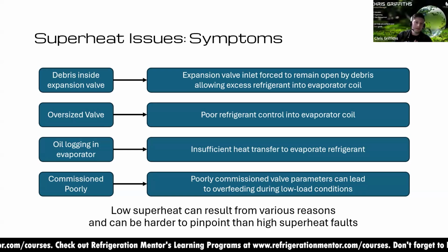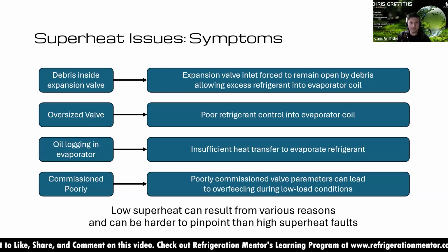So honestly, having that visibility over a prolonged period of time is invaluable. And learning for troubleshooting, literally yesterday alone, I was chatting to one of my former apprentices who's now an installation engineer, and he was commissioning a small freezer room, and he was wondering how long it was going to take before he heads off because he's got a 2-hour drive home. So I said, I'll dial into the site, have a look, and you can see it's dropping by 5 degrees Celsius every 5 minutes. I said, well, you're plus 2 degrees now. You've got to get down to minus 21. You'll be home in ideally 25 minutes. I think it took about 30 minutes in the end because someone had opened the door.